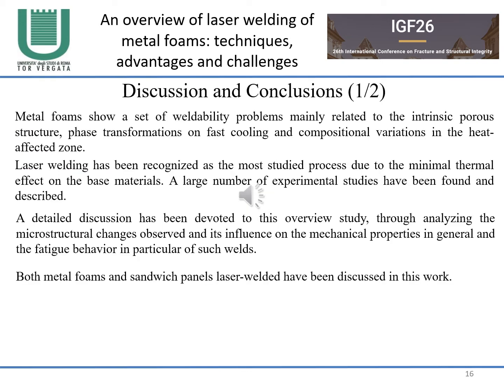Metal foams show a set of weldability problems mainly related to the intrinsic pore structure, phase transformations on fast cooling, and compositional variation in the heat-affected zone. Laser welding has been recognized as the most studied process due to the minimal thermal effect on the base materials, and a large number of experimental studies have been found and described.